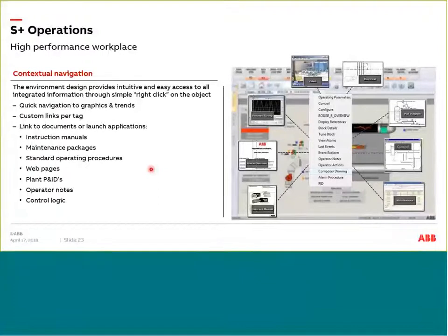Say you go to your second graphic where pump 2 is. It's the same CCTV, but I can right click and show me the pump. Now it'll zoom out of pump 1 and then zoom in to pump 2. So you can integrate video, electrical drawings, P&ID drawings, or even control for that matter. If an operator wants to understand what's causing an interlock, the operator can right click on the tag and it'll bring up the S Plus engineering CLD, or control logic drawing. So the operator can see the live values going through the logic. Of course, the operator cannot modify it, but he or she can know what's happening and troubleshoot any interlocks.